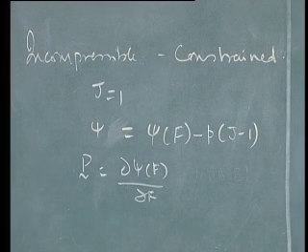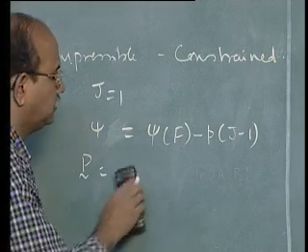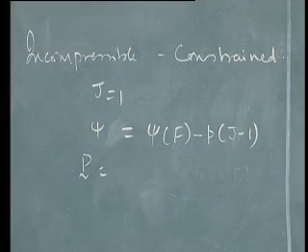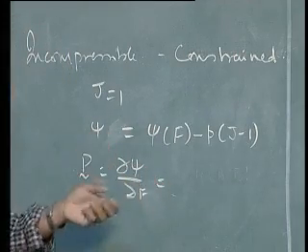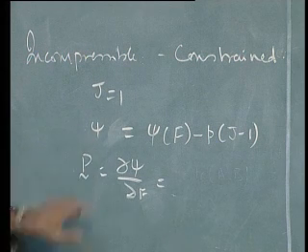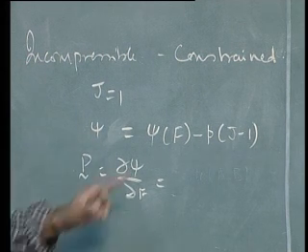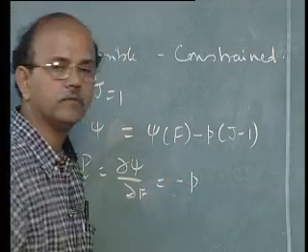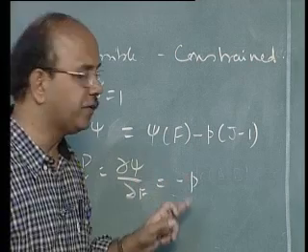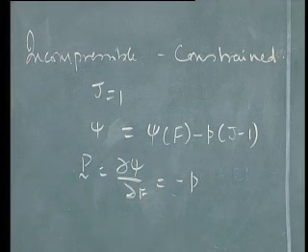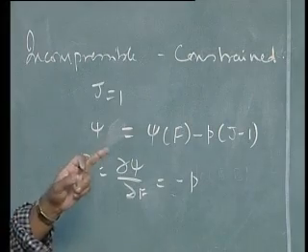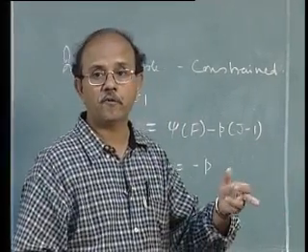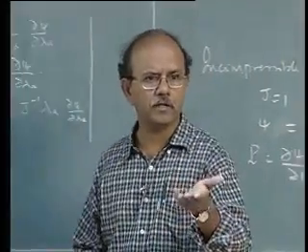So instead of that, we now have to write down the derivative of this strain energy function, which is put forward here, and so that becomes minus P dou J by dou F. Remember that yesterday we derived this. Look at what we did yesterday. What is J? Determinant of F. Dou of determinant of F by dou F. We did that yesterday.